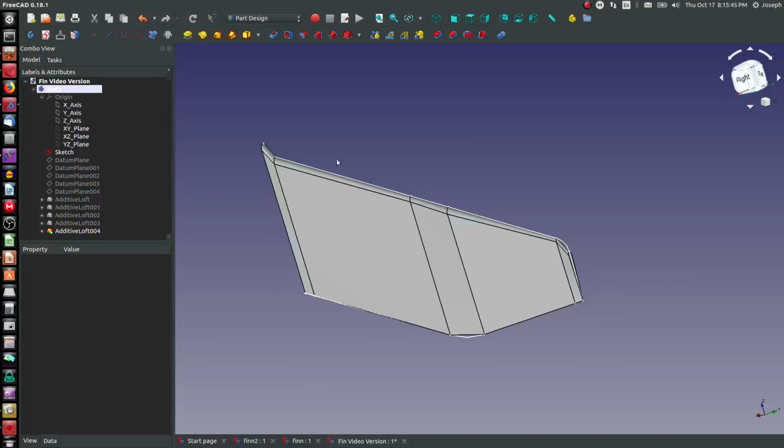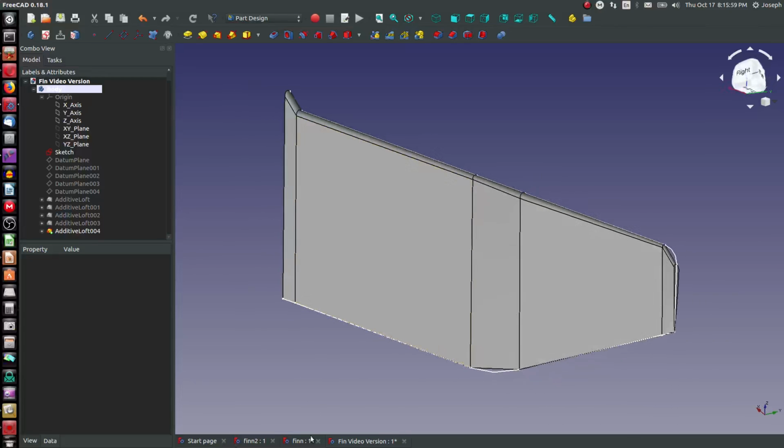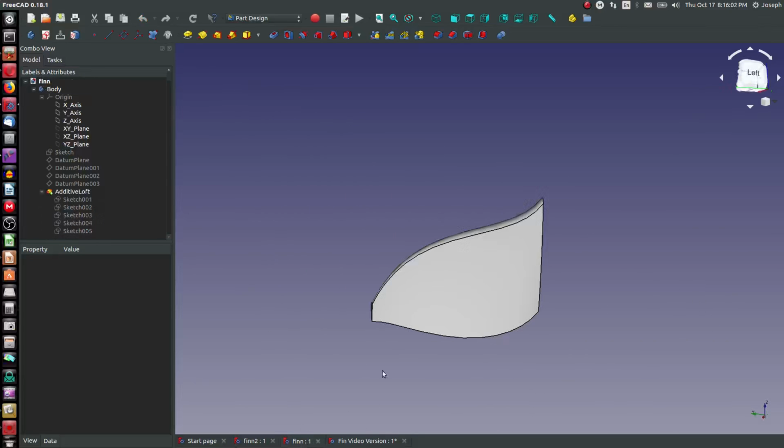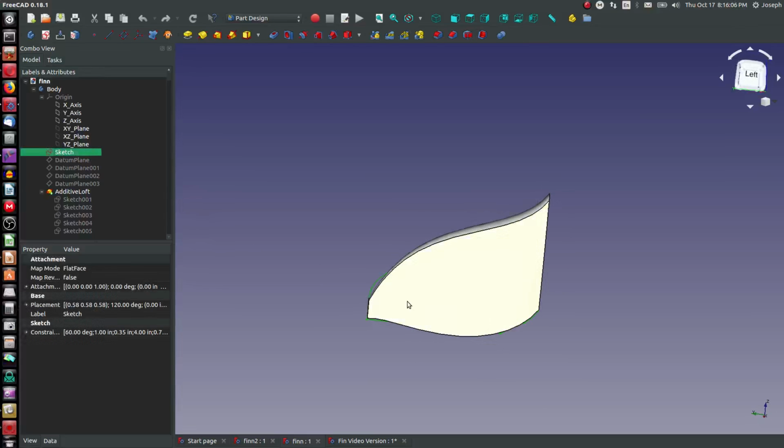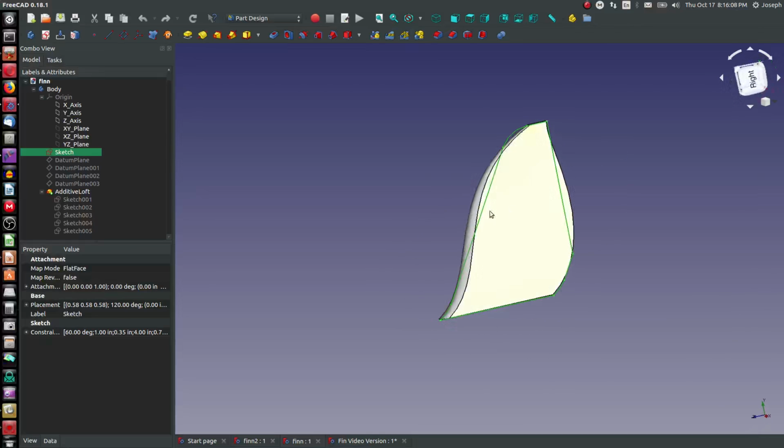If you do want to have curves and radii, make sure you have a lot of profiles, especially around radiuses in your overall boundary, because that will smooth it out. It will make something like this a lot more precise to fit within the boundary that's been set for it.